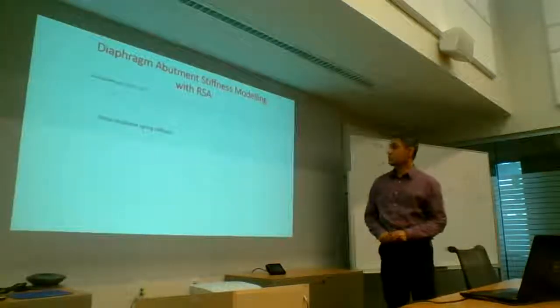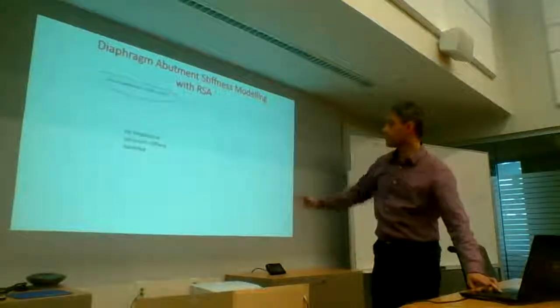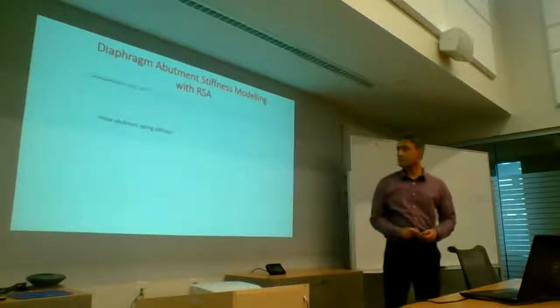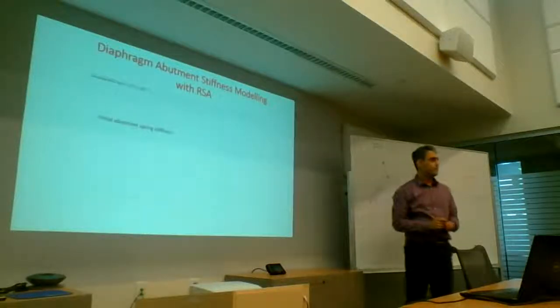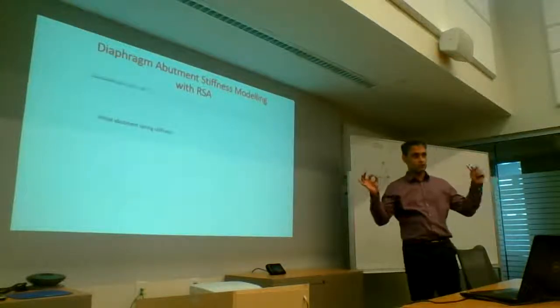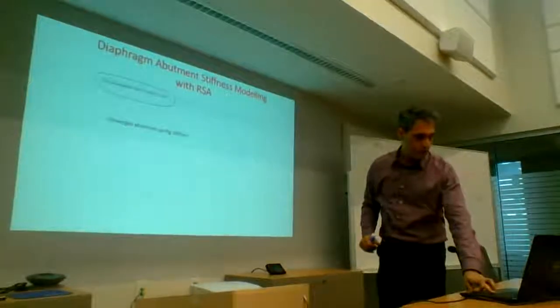That's what I'm getting. Now I put the initial abutment stiffness, which is 4,300 something, and my period drops from 2.6 to, look how drastic this is, 0.63. Day and night difference. Because I put in a really strong, really high stiffness. Okay, fair enough, it doesn't move much.